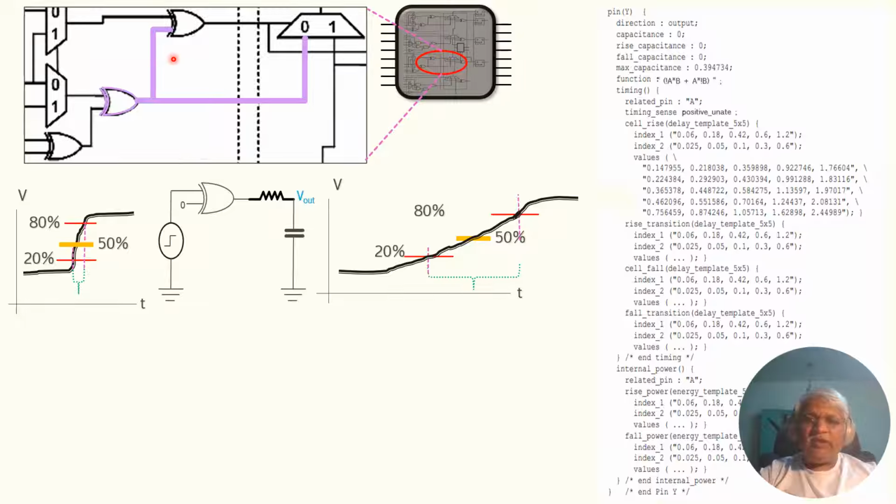Whether one buffer is needed here or no buffers here depends upon how much these nets contribute to the load. That means the input pin capacitance of this, and in some cases there are more fanouts. So this net and this net need to be handled uniquely and differently.